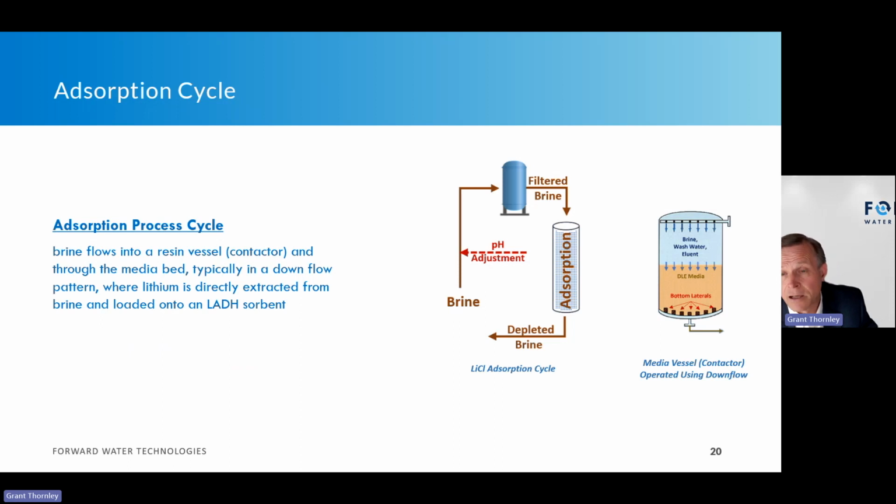Next, if I do a pH adjustment, sometimes I may precipitate solids out of the brine, depending on what the characterization is. So let's say I've got calcium and I'm bumping it up, and I used sodium hydroxide. Well, I may have magnesium hydroxide or something drop out, or calcium carbonate drop out. So this is why it's important to have a filter downstream or after your pH adjustment. So this is going to, I jokingly refer to, take out the sticks and frogs and body parts.